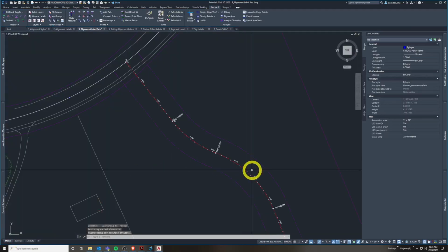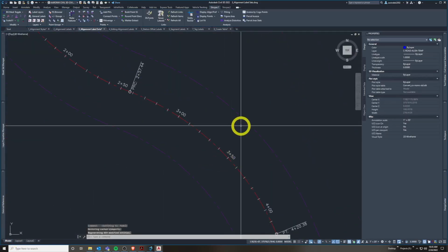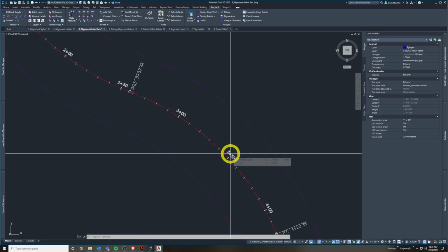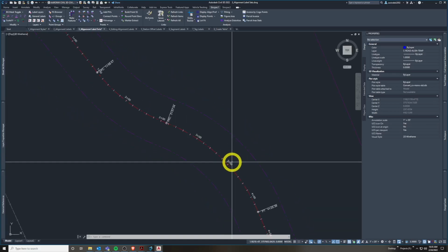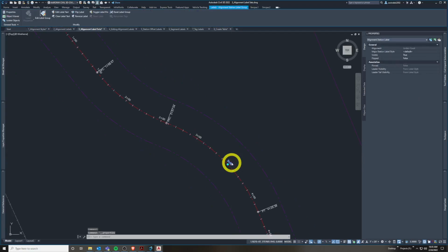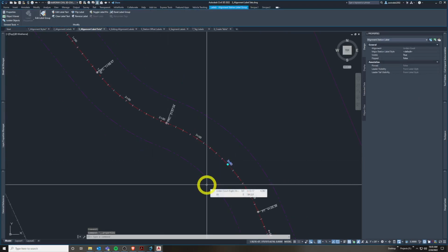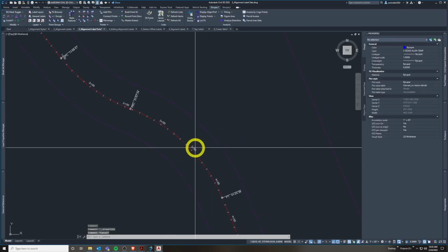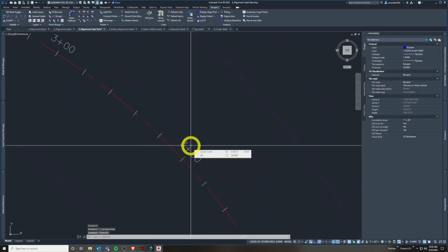So that's just lessons about viewports, how they interact with model space, and the dynamic annotative scale of Civil 3D text is very powerful. AutoCAD annotative styles are just as good, but they're much clunkier to use. These generally work a bit better, the Civil 3D styles in the text and all the labels we're learning how to use. Once the styles are set up the way you want, they generally work pretty well.